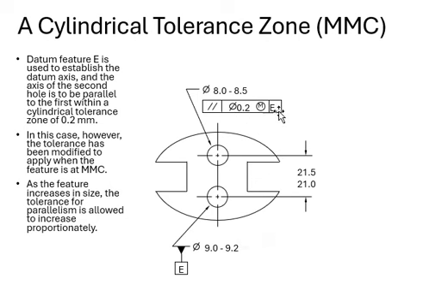And we have our control zone right here, a tolerance zone of diameter 0.2, got to be in that range, and we want the maximum material, meaning the material of that part has to be max, so therefore this tolerance is 0.2 around there. We're looking at the parallelism of those two little cylinders, and then of course our reference plane right here is your E, which is this plane right there.